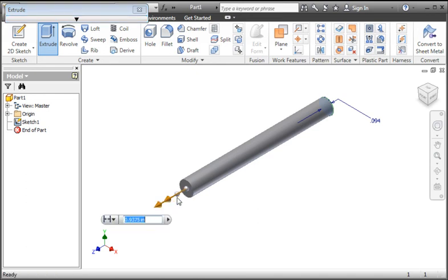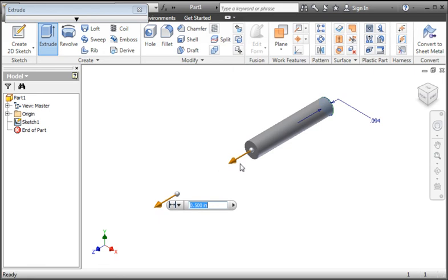You can drag the arrow to adjust the length of the extrusion, and notice that the Mini-Toolbar moves along with the geometry. The purpose of this type of interface is to keep your focus on the feature while you adjust it, and your eyes don't have to travel very far when you enter values in the toolbar. While you drag the arrow, the values in the toolbar snap to increments of 1/16 of an inch. I'll show you how to set this setting in the next lesson.